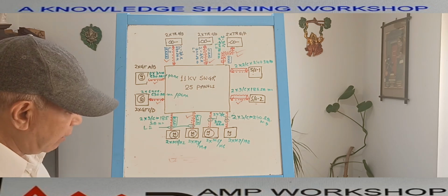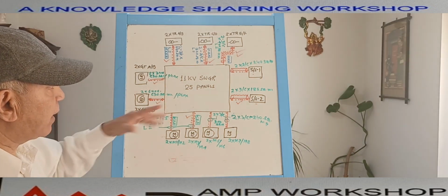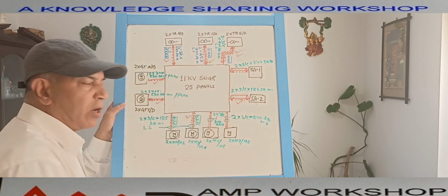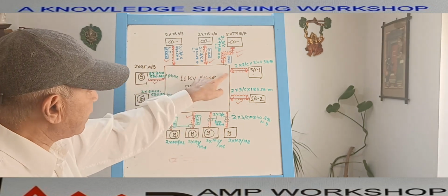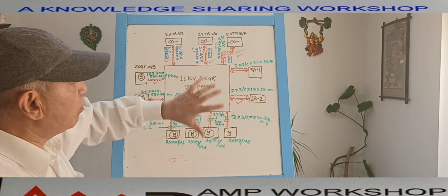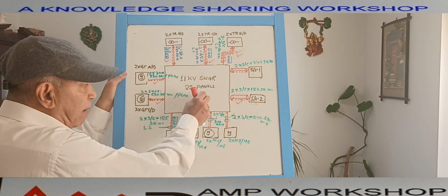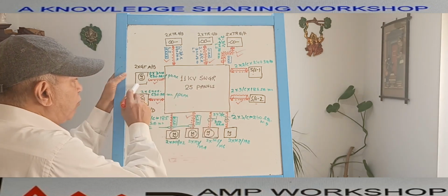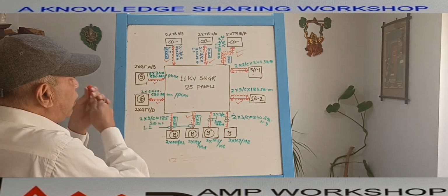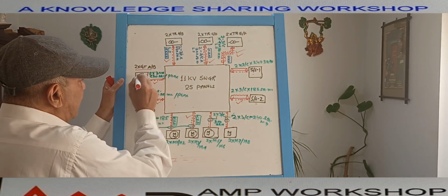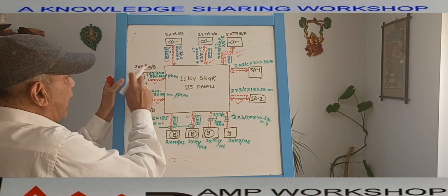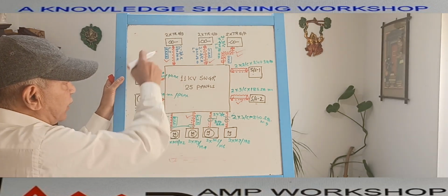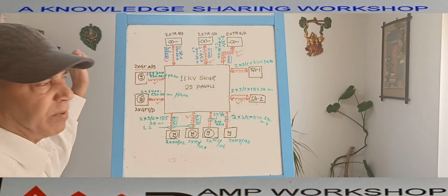Okay. Now, how are we representing the cable block diagram that I have shown now? You see, these are the various symbols we have used here. This is how the cable block diagram is made. This is the master equipment from where all the cables originate, so you can say indirectly this is the power source. This switch gear is connected with 4 generators. Here, 2 into GT A B means these are identical generators: 2 in number, tagged GT A and B. If you have space, you can put the 2 generators separately. As I have limited space, I have represented it this way.